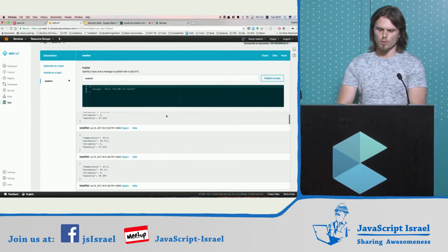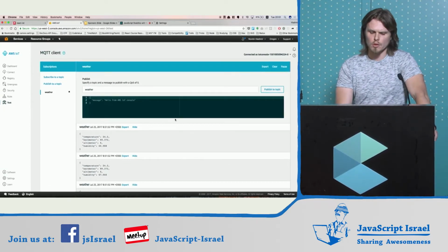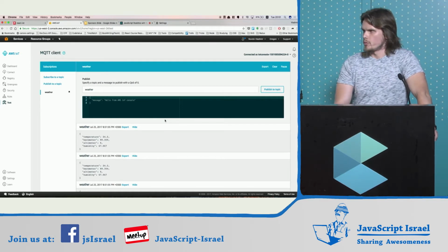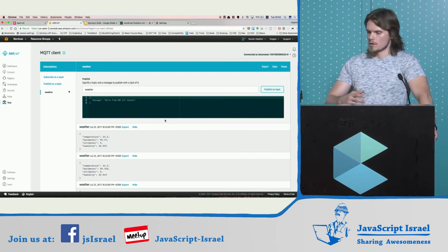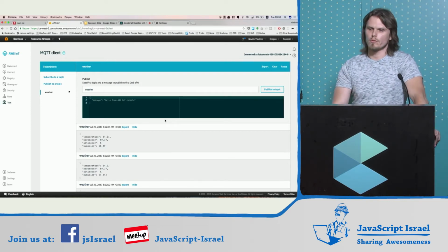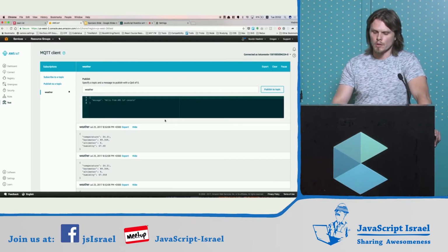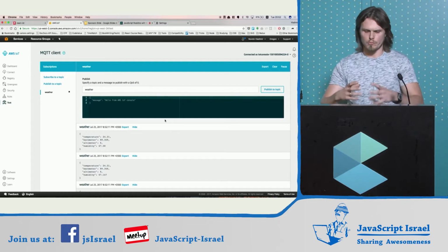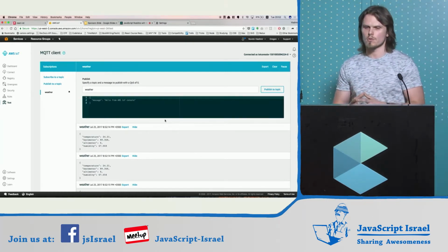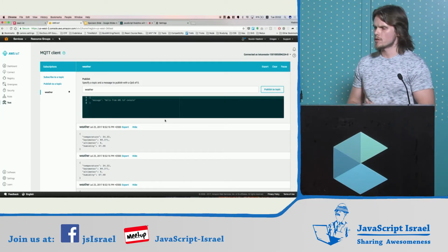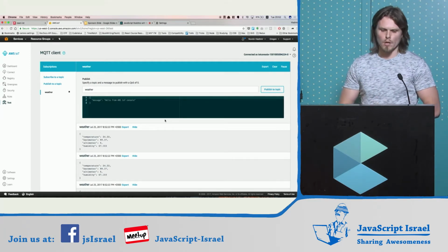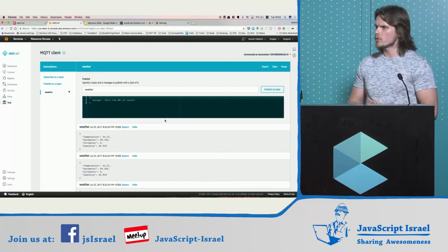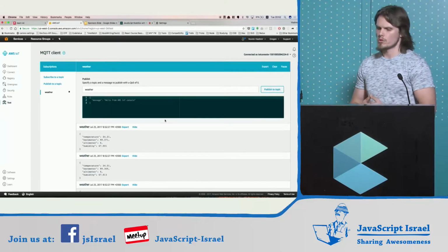We need to subscribe to some topics. We will look at the code in a bit. But basically, if you want to build a connected device with AWS, with the whole scaling ability of AWS, it basically means you need to take some system on chip, some SoC, connect it using the AWS device SDK, and connect it to the AWS IoT cloud. It's connected not through the HTTP protocol, it's connected through MQTT, which is a messaging protocol.